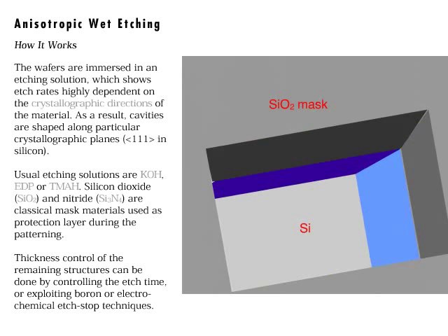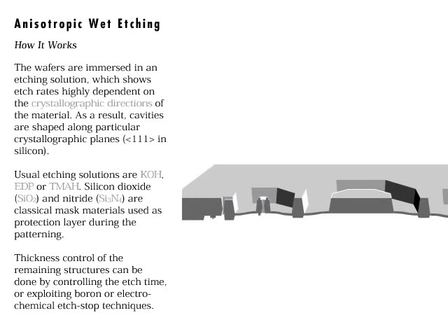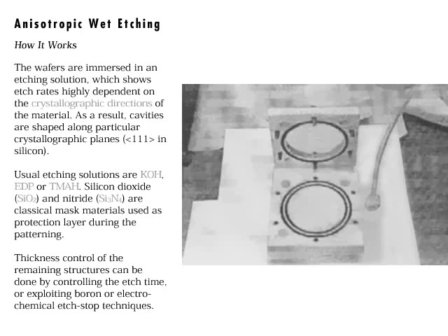The etch process is highly sensitive to any misalignment of the mask with the crystallographic orientation of the wafer. Complex forms can be produced by exploiting anisotropic etching of both sides of the wafer, the etching operations being carried out simultaneously or sequentially. For the latter, backside protection of the wafer is needed and can be done either by applying a coating of mask material or by mounting the wafer on a specially designed holder.